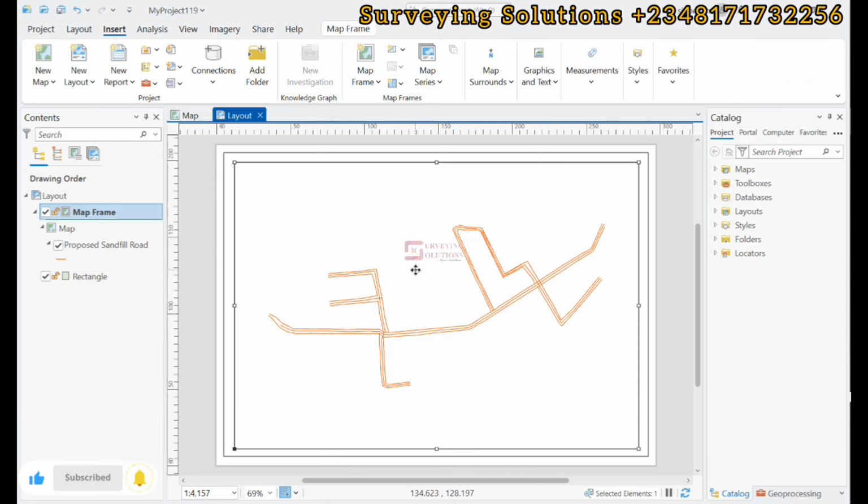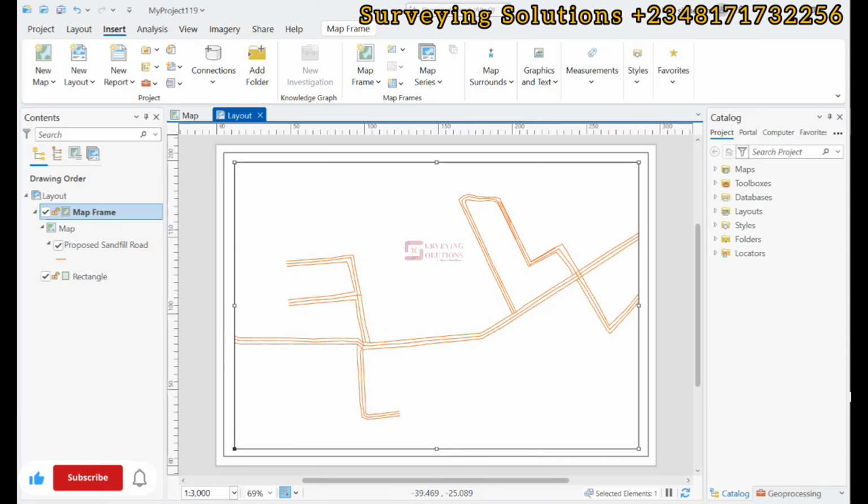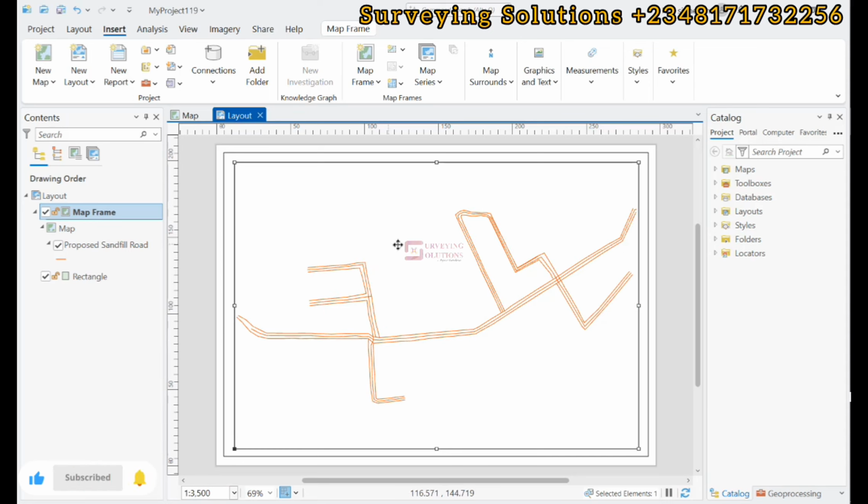The next thing is that we can see that we still have a few spaces, so we can decide to modify the scale. So this is 4,000, right? Good. So we can decide to take it to maybe 3,000 or 3,500 to see how it best occupies the whole space. Okay, so 3,500 is good. Having established that, the next thing is for us to now add the grids.